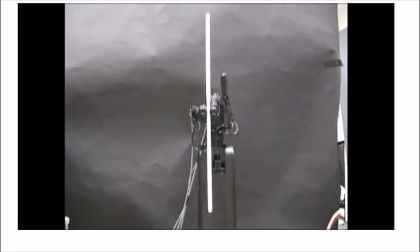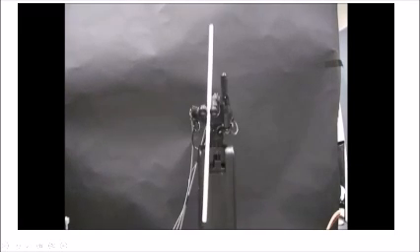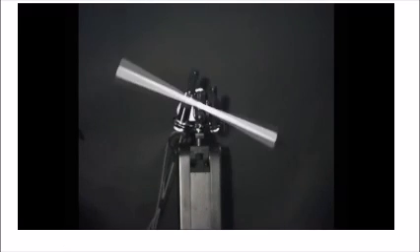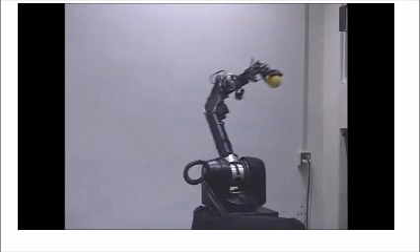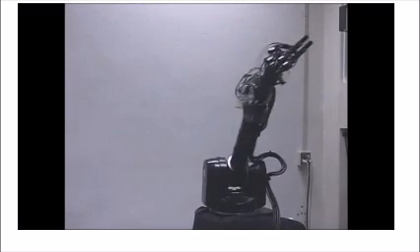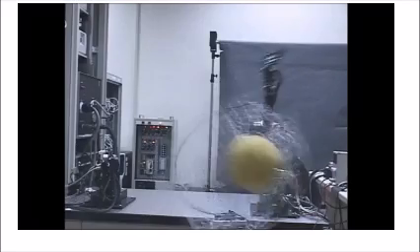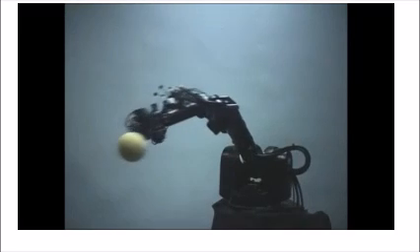This is pen spinning. The task is achieved due to the stability of objects experiencing high-speed rotation. The contact force and the timing of shifts about the axis of rotation are modified in real time by tactile feedback. This is throwing. The release method is designed so that the error of the ball direction is reduced by the apparent force, which is generated by a high-speed arm swing.